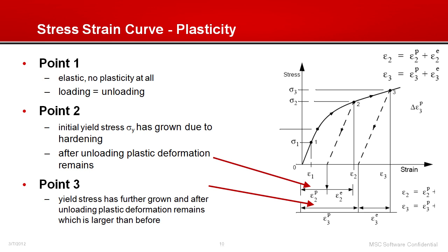The stress strain curve has a linear and a nonlinear stress strain relationship. There are a couple of important items to derive from this stress strain curve. The first one is the linear portion. For example, sigma y is the yield strength of the material, which characterizes the linear elastic portion of the material, which means at any point in this portion of the curve, upon unloading, the material will go back to its original position.